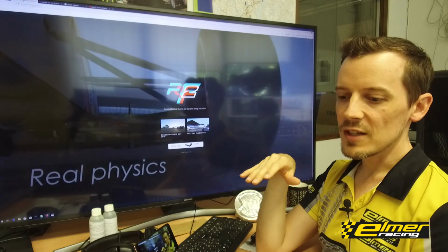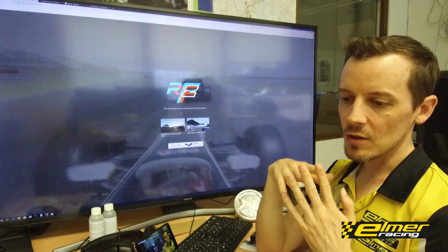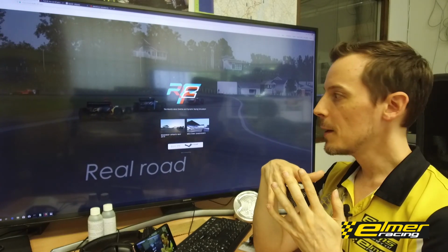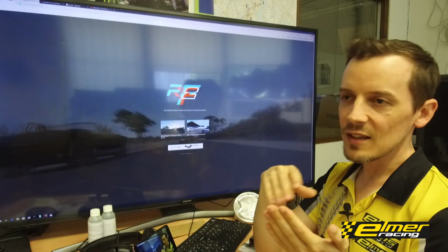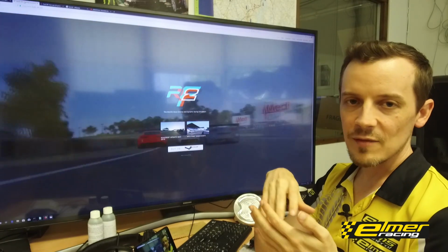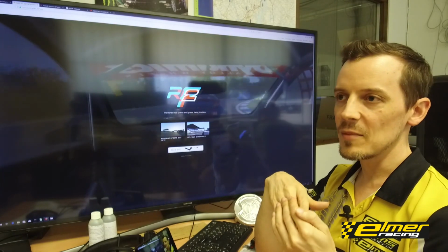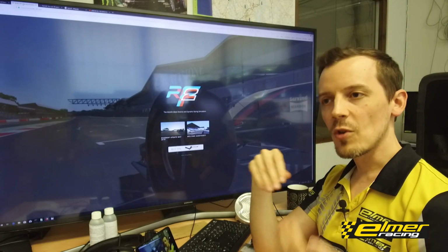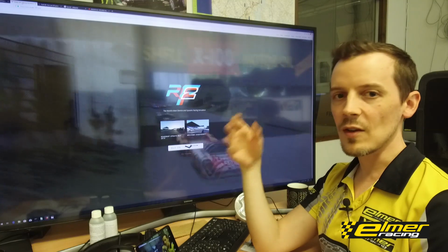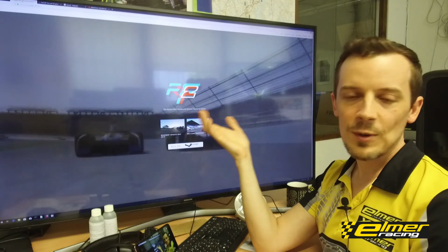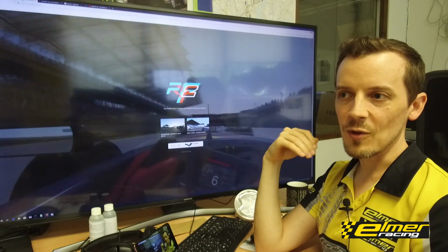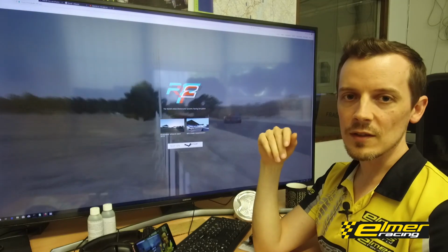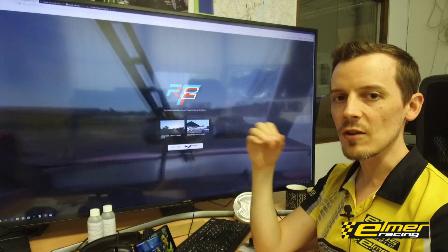be doing so many compromises, optimizing your cost, basically. That is the most difficult optimization process for a race car project. And you can check, okay, we need whatever differential that is available cheaply, or gearbox or something, and there can be easily 40,000 euro price differences between these kinds of components. And if you can run a more off-the-shelf component that you can make the car work with, then that's 35,000 euros potentially that you can save for doing a more advanced aerodynamic package on the car that is going to potentially influence the car performance much more, if you can get the car to work with that.